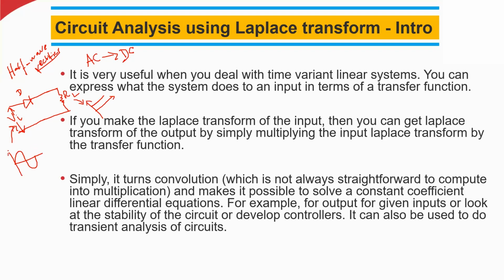X-axis, Y-axis. Okay. So technically, this is not exactly pure DC. You see here, pure DC is like this. But here, the voltage is like this, and then like this. It's called pulsating DC. And then we have to use some filters and regulators and convert this pulsating DC into this pure DC. That is a different operation.